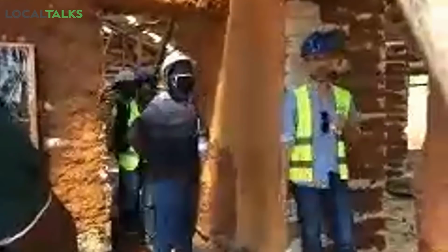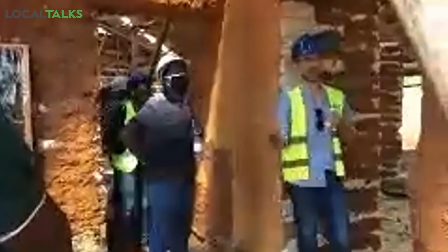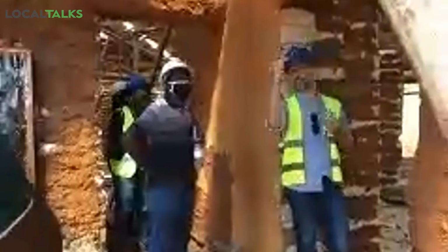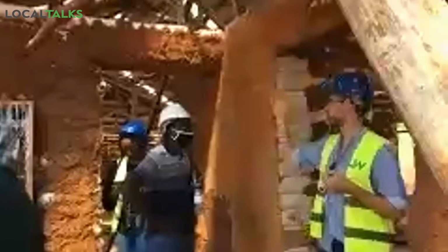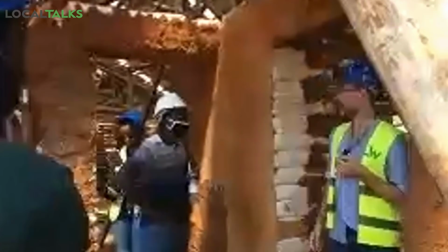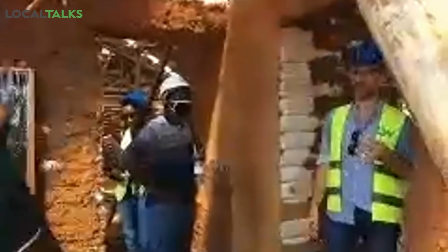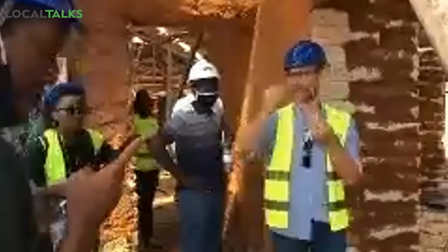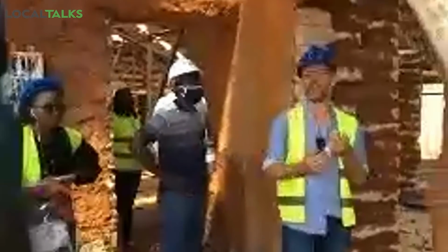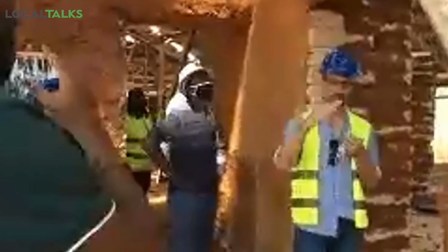And from inside, a woven mat ceiling throughout. Notice these very many translucent strips that we have inserted into the roof. They will be eventually much narrower because the eucalyptus offcuts will protrude over it if you want, and only leave a very small gap. Essentially, one of the offcuts is missing, and that is where light will enter, and that light will then again be filtered through the mat.